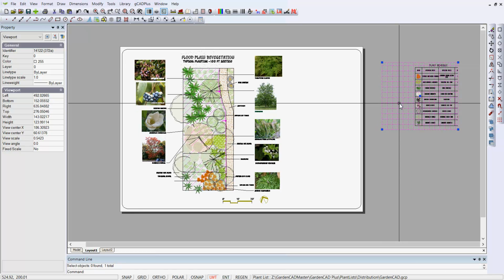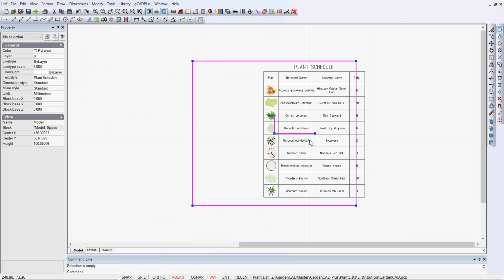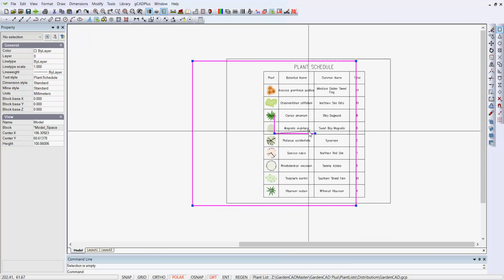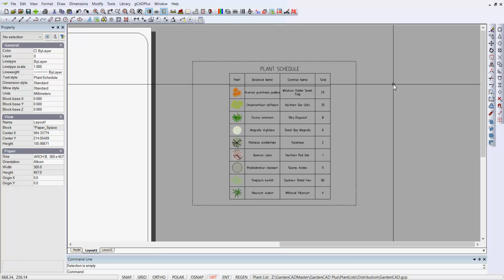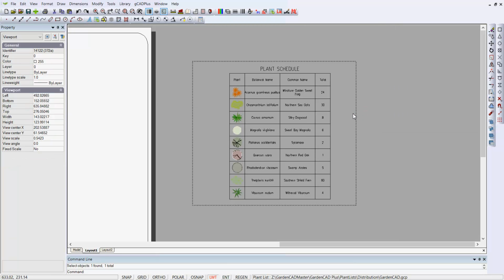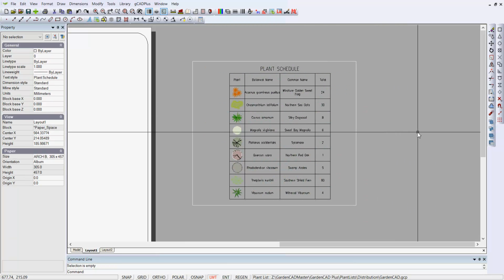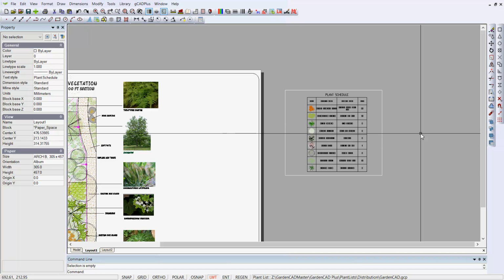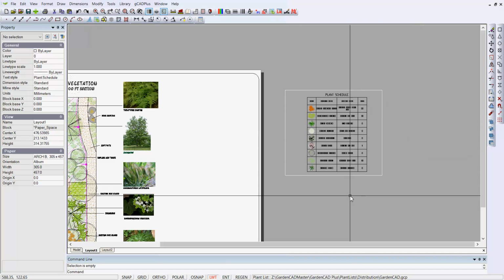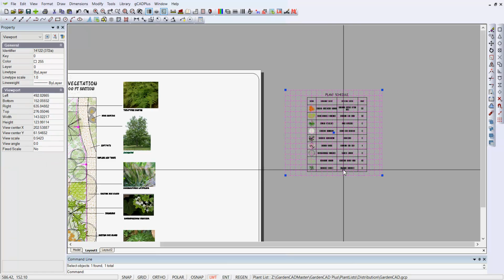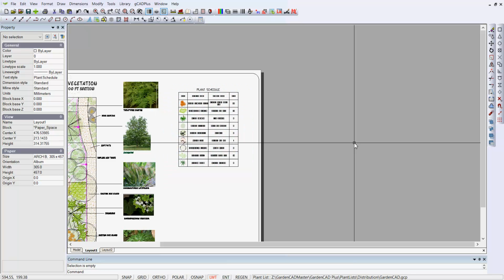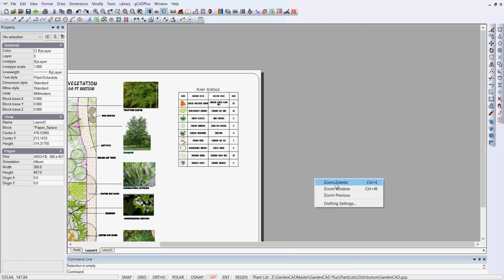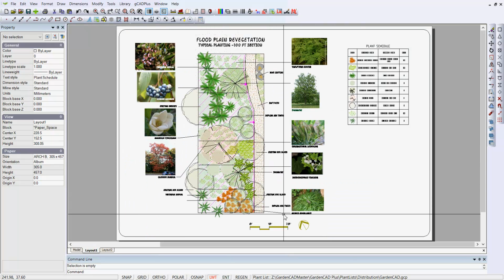We double click in here and dive in, and we can set our view box around the area we want and display it on the layout. So here we are. We have a floating viewport with a white background so it won't see on the sheet, and now we can move it into position, and there we have, we zoom extents now, we have things laid out nicely.